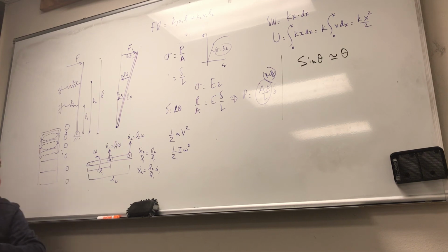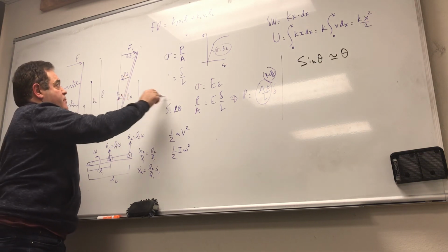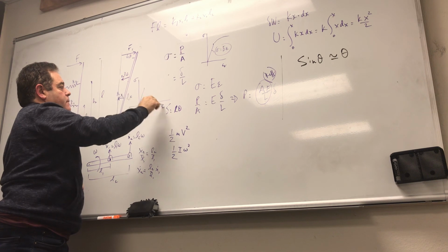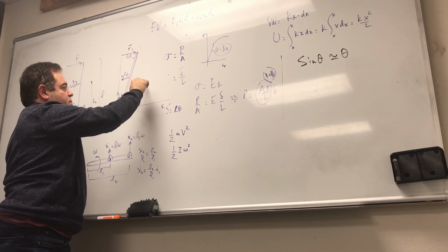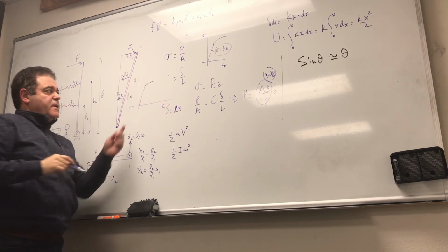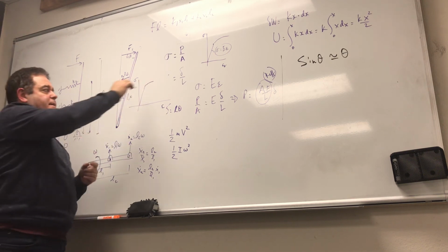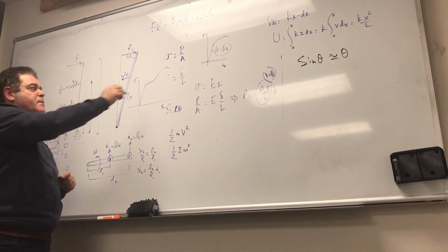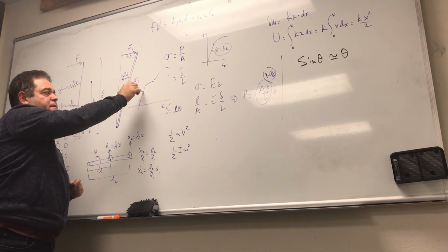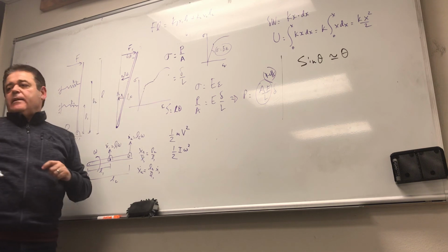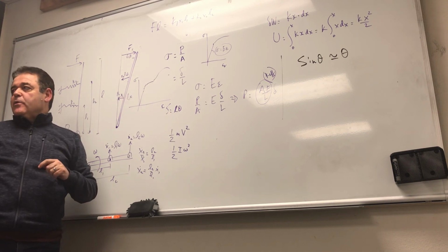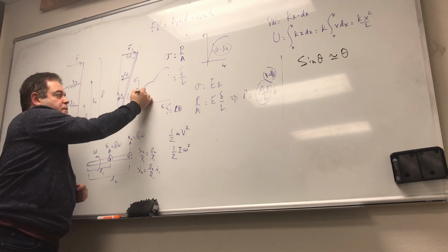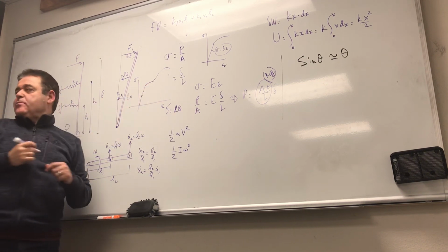Remember in material science where you have the stress versus strain curve, right? At a certain point, what happens? You reach yield point, and then obviously it does this, and you get fracture and all that kind of good stuff. But if you go to there, load the system to there, and then remove the load, what happens? In which trajectory should you go back? You go this way, and then you come back exactly this way, right?